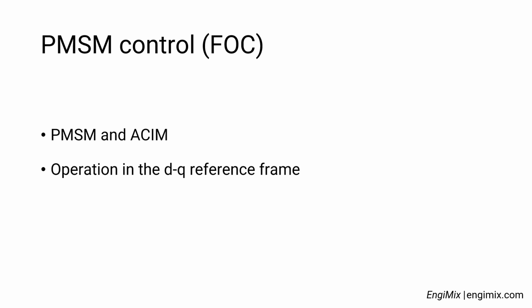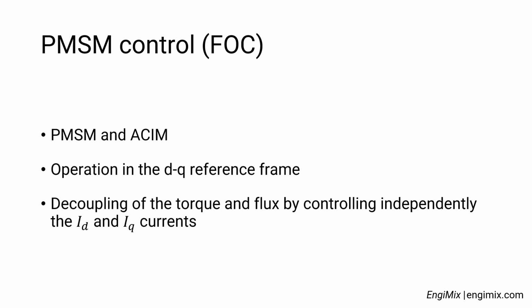Let's speak now about the PMSM control, and more specifically about the field-oriented control technique. The field-oriented control, also known as vector control, is a technique used to control permanent magnet synchronous motors and AC induction motors. It works in the DQ reference frame and uses mathematical transformations to decouple the motor's torque and flux.